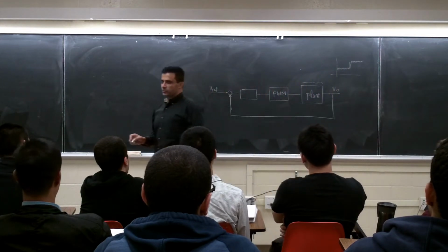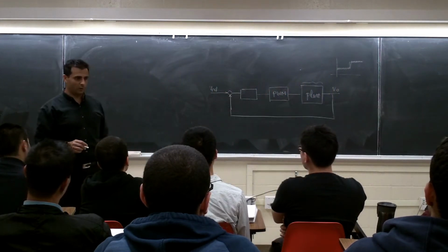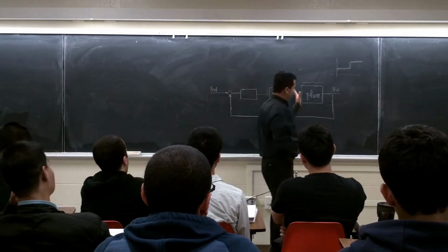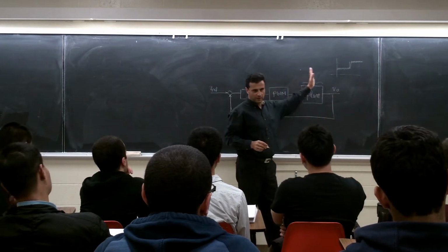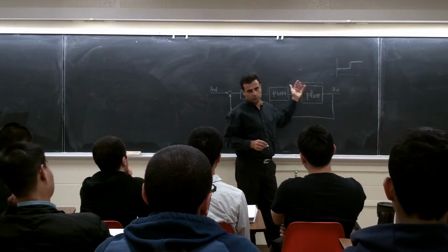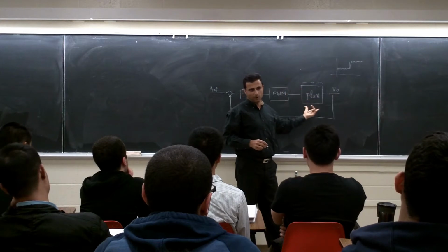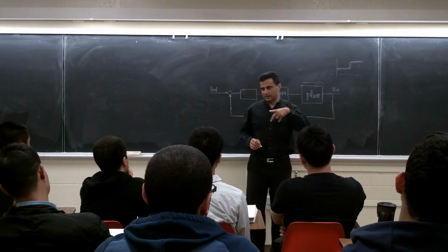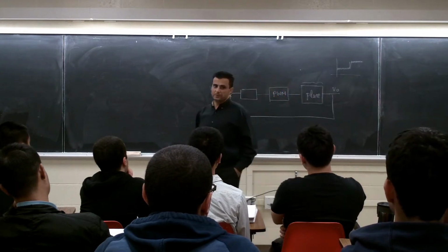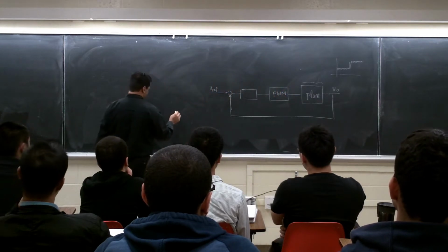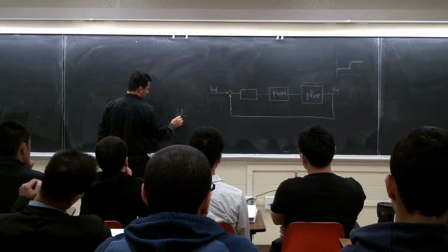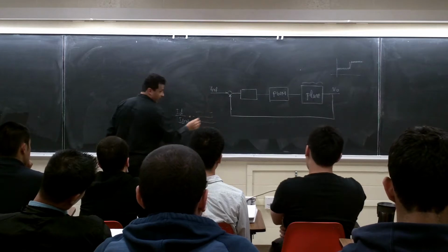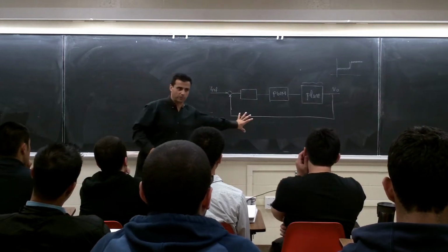To do this, there is a method, they call it a small signal model or linearization method. What we do, we linearize the model of this power plant, be it a buck, boost, whatever converter it is. We linearize that model, and we'll find a transfer function for this. If you look at the inverter, remember what we did? We said ID over ID ref is a transfer function, right? And you can use it for your control purposes, right?